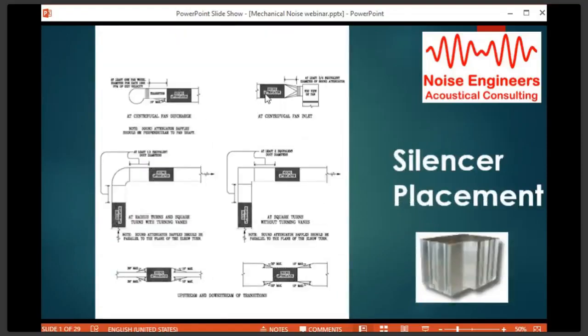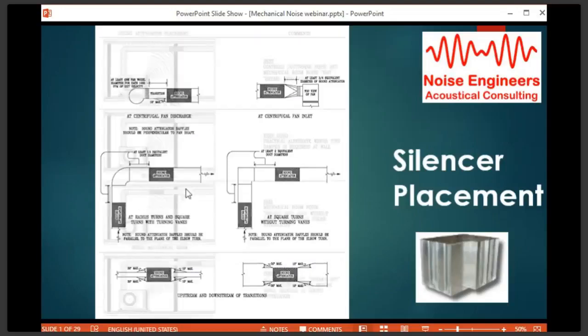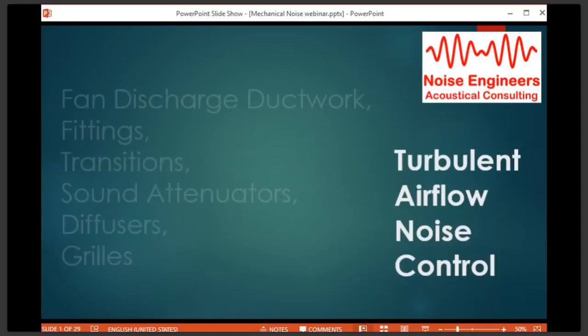What else? Same thing with the flow. These silencers are going to constrict flow. You don't want to slam all of the air to one side or the other. You'd like the flow to be as even as possible. There are elbow silencers, all types of silencers, and you just want the flow to be as even as possible, so it's as effective as possible.